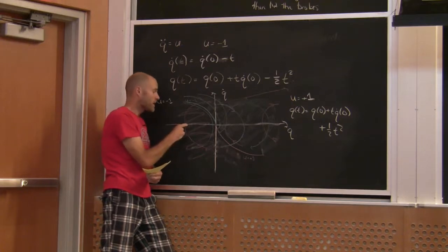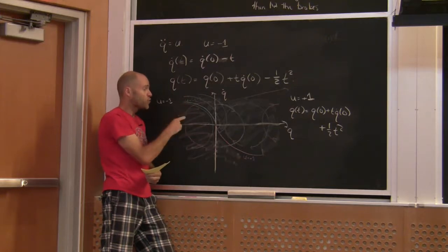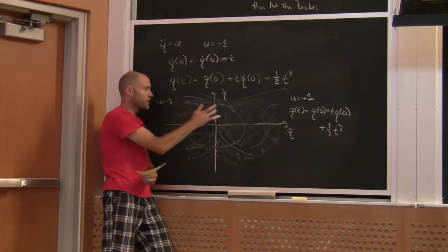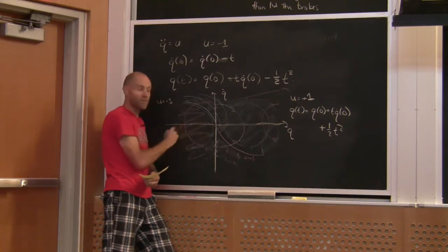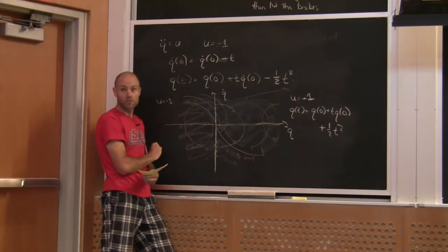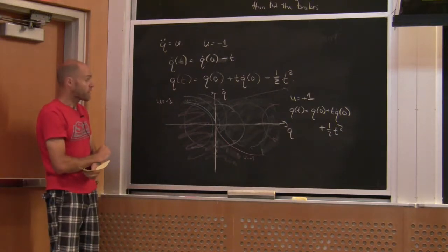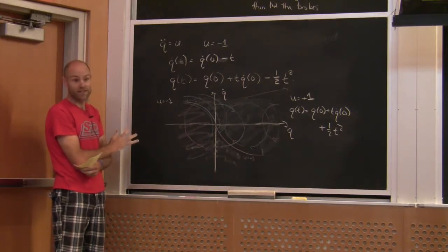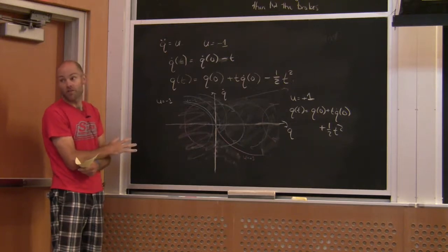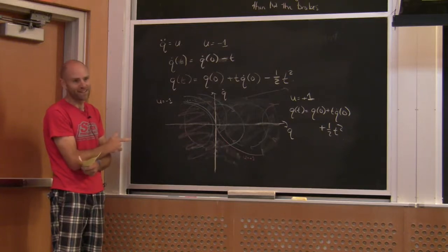It tells me no matter where I am in state, position and velocity, what action I want to take. It happens it's only u equals -1, or u equals +1, and then maybe 0 at the origin. We want to be stopped at the origin; at that single point, we'll choose 0. Does that make sense? I want to put that up there because this is going to be our litmus test. If I show you some numerical algorithm in a few minutes and it can't generate that, then you shouldn't trust what I'm saying.